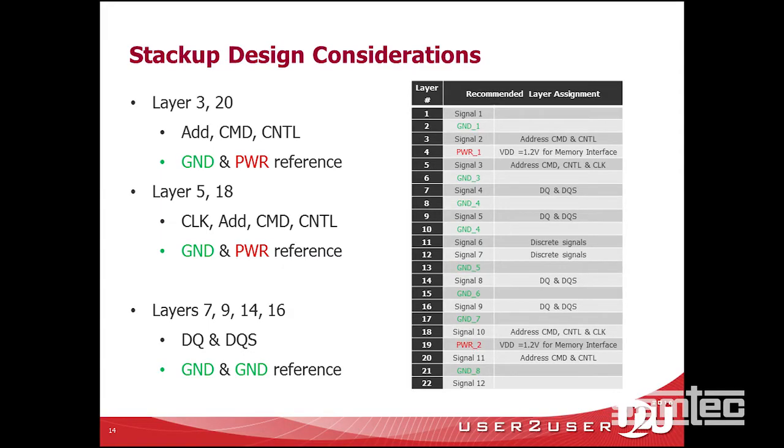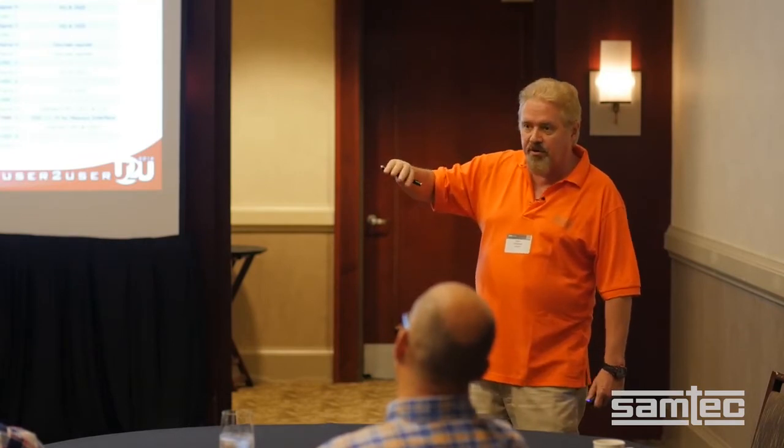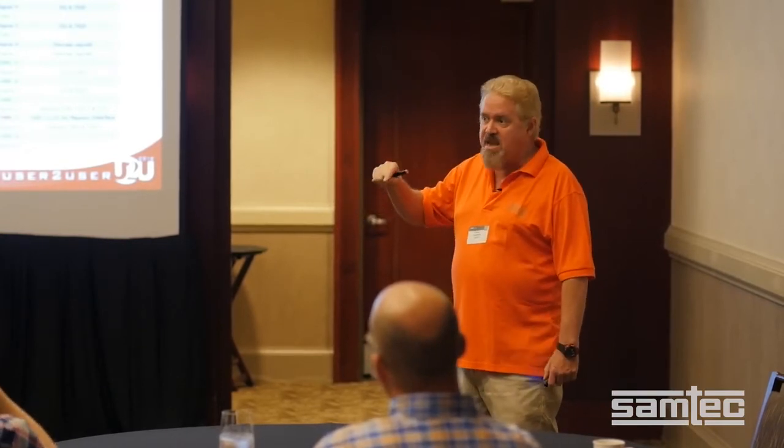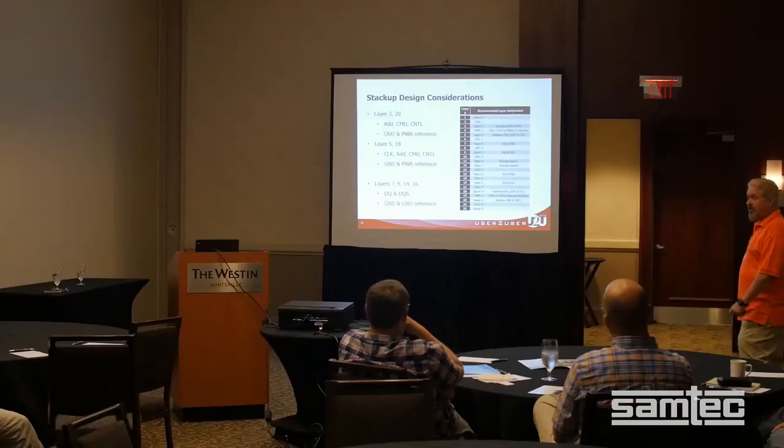The easy answer is, it should be in the controller specification. Don't you have a printed circuit board in your controller? Of course, your substrate. That sets the references because they set the traces next to a reference. That's your reference return current plane, and you need to keep those consistent. Just don't route them out of your controller to any layer you want and then up to the RAM. It might not work because then you get split planes and reference changes, and that's not a good thing.